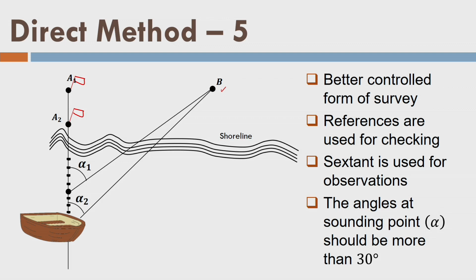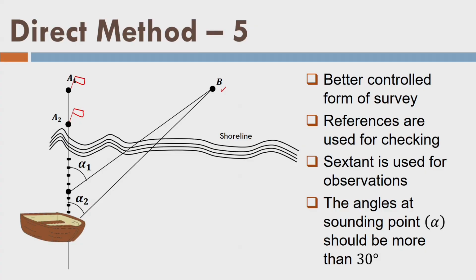Now we can see that we are measuring the alpha angles at certain intervals, maybe every 10th reading. What about the intermittent readings? For the intermittent readings, we take only the distance measurement using the time, assuming that the boat is moving with a constant speed. In order to find the angle values for the intermittent points, I will use some kind of interpolation.